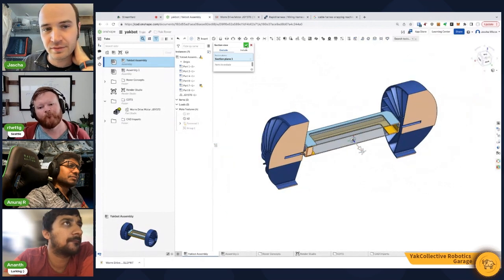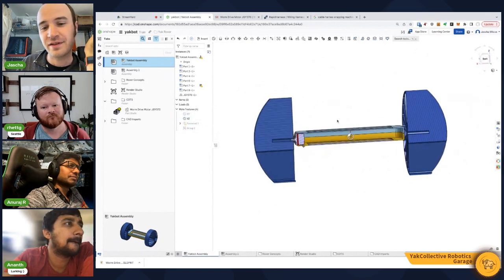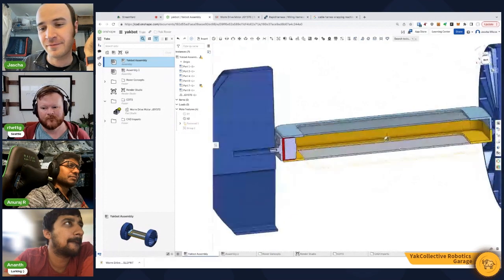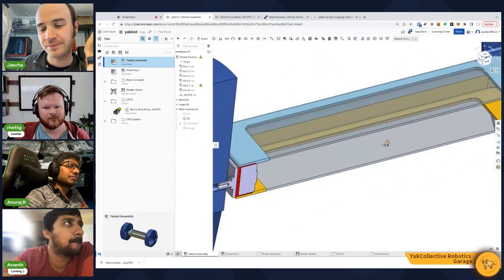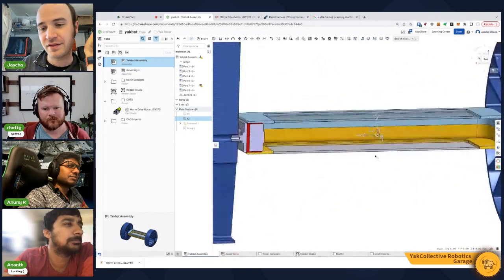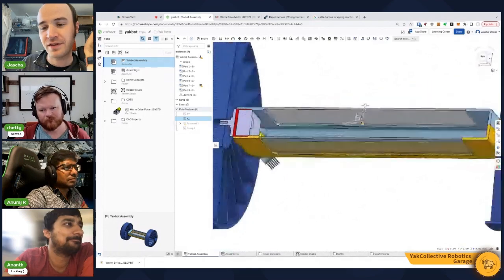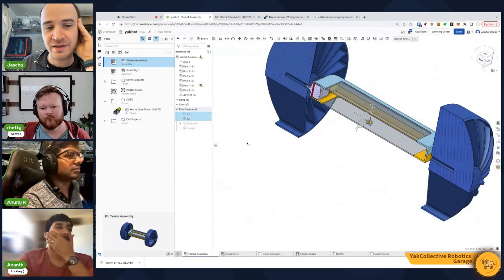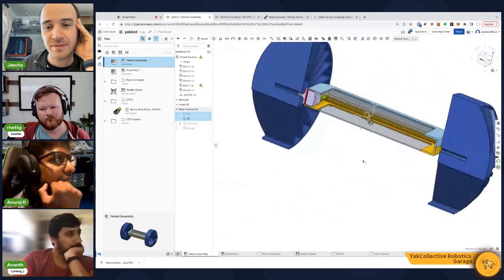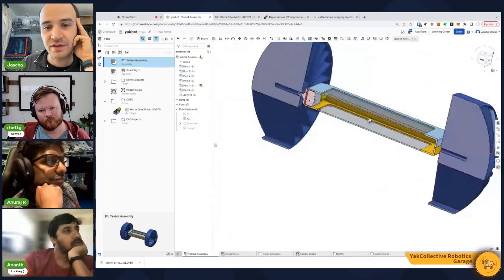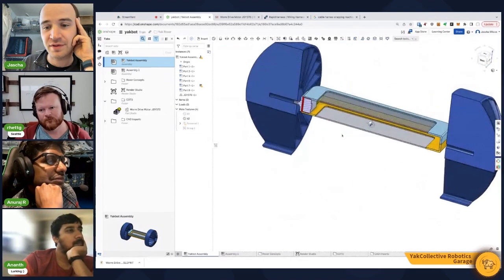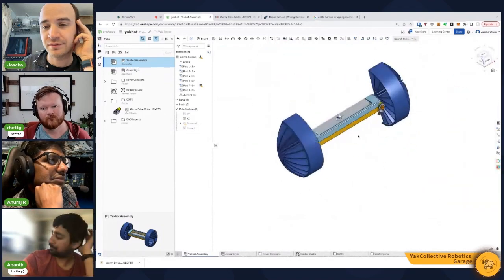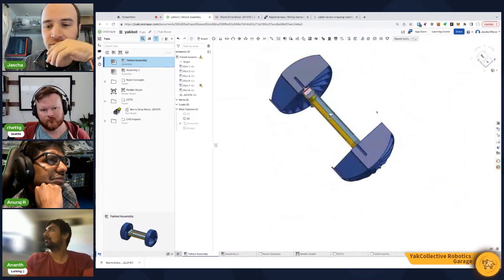Yeah. So, when you click the mate connector, I think it's kind of a weird thing. I should probably push back on them to name it something else, but this defines a plane as far as section views are concerned in assemblies. So I'm almost always adding these two anytime I'm in a new assembly, just to facilitate section views, which is an extremely common thing to do. But anyway,